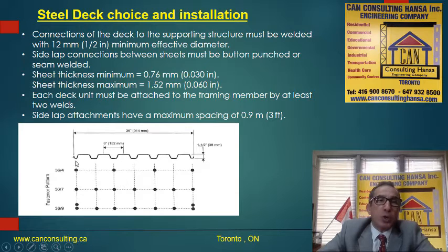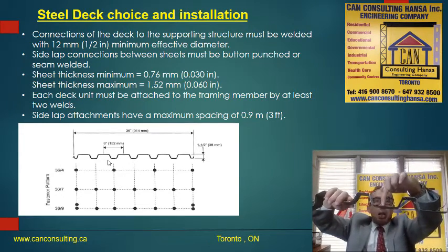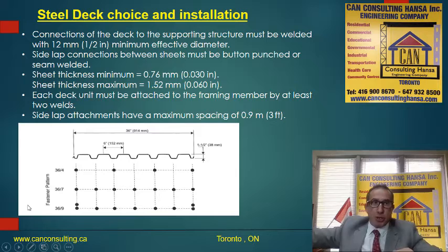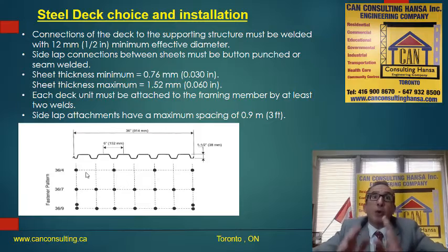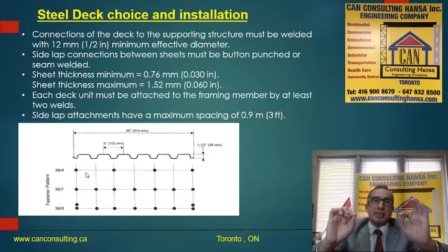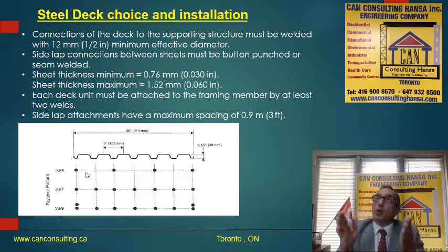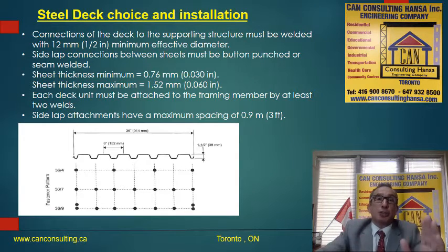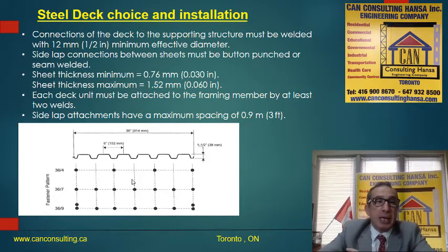When you install the steel deck, the beam comes underneath it, like my hand like that. Then you can weld the steel deck from the lower point, from the flutes, to the top flange, and you have different patterns of welding. Based on this pattern, if you are a structural engineer, you have to specify the pattern because that can give you the flexibility index for the diaphragm. If you are a construction manager or project manager, you have to follow the structural drawings and guide your installer about the different fastener patterns.